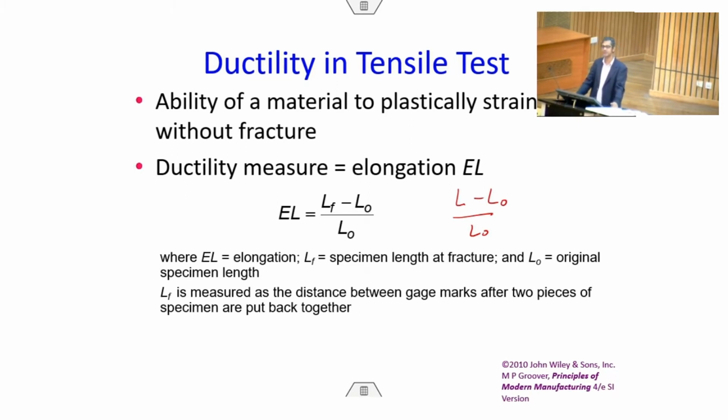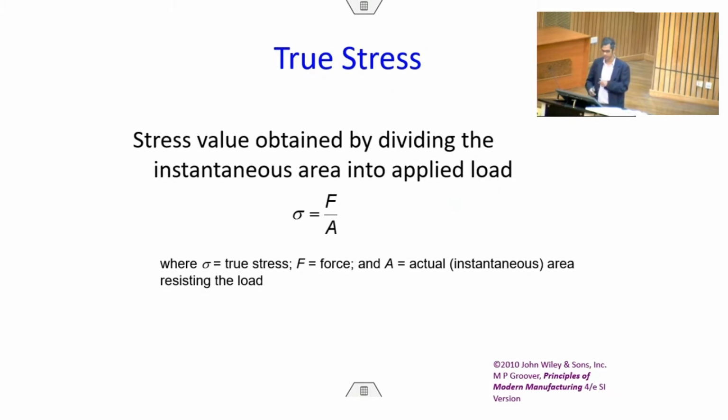I have shown this in the last class also. Specimen geometry as per ASTM standards has two marks on the sample. That is what is known as the gauge length. That corresponds to L0, and LF is whatever is increasing because of the application of the stress force.